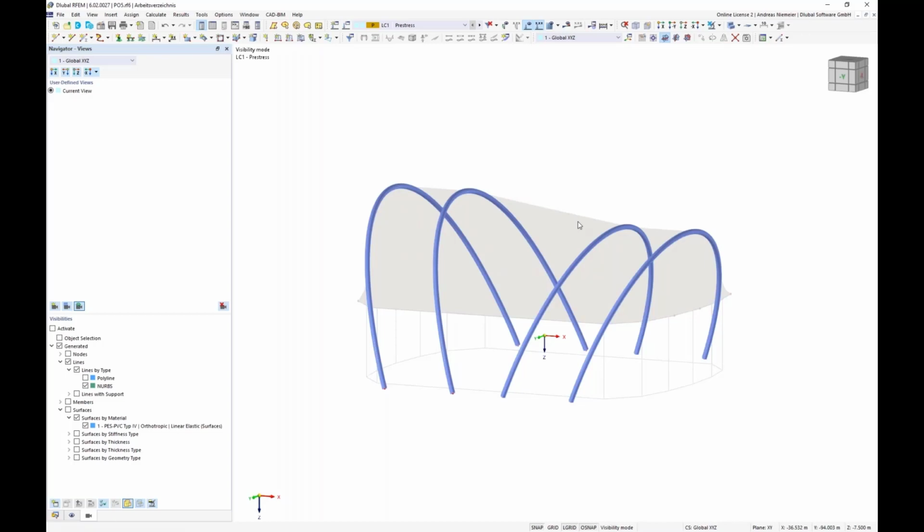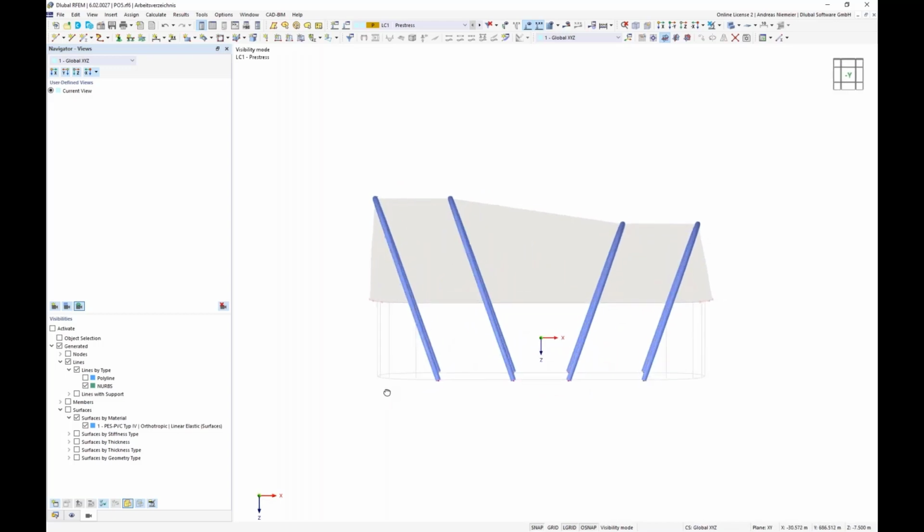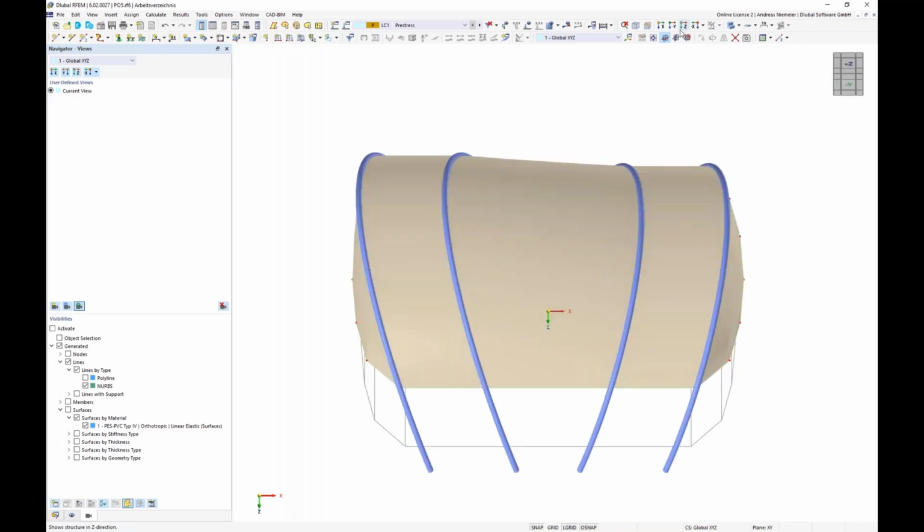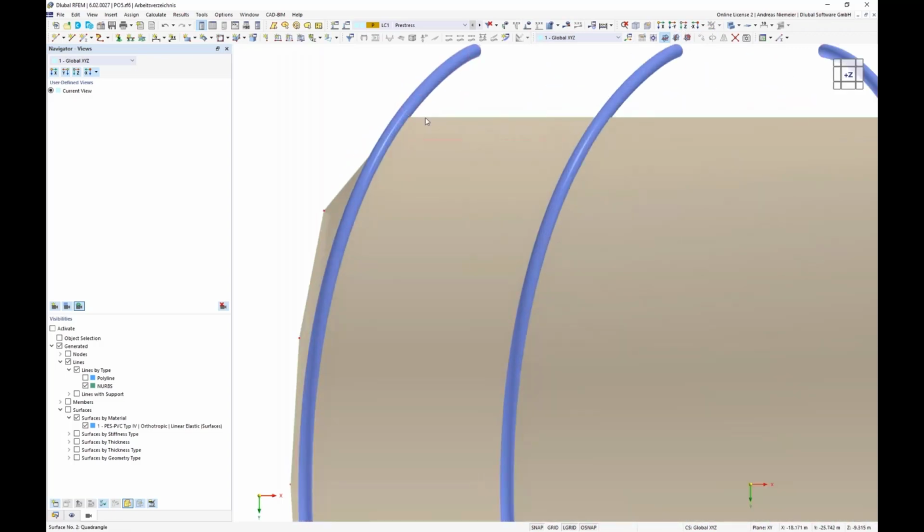It's now not only graphics, and even the stiffness terms are added here, and the membrane connects to it. But if you watch this, it will not be stable because the beams are not linked and have no bracings. So let's start with the linking, producing truss beams here in between these division nodes. But when we take a closer look, you will see that we run into an issue because the membrane edge is exactly on the place where this linking beam should come.